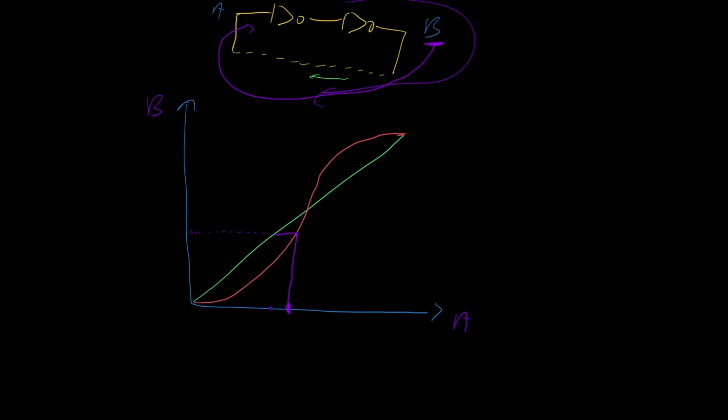So let's do this again. Assume this is the input voltage. We go up to the red line to find the output voltage. Now I want to read off the output voltage, say it's 2 volts, and go down to the same position, 2 volts, on the input axis. To go from the output to the input, well, this green line does that. It does the reflection for us. So if I want to go from a 2 volts output to a 2 volts input, I go across to the green line and then go straight down again.